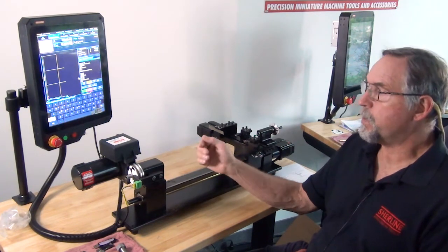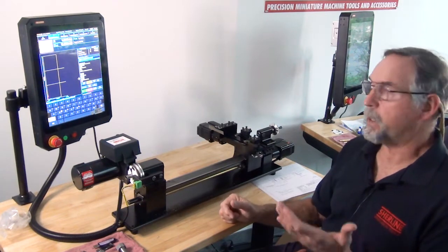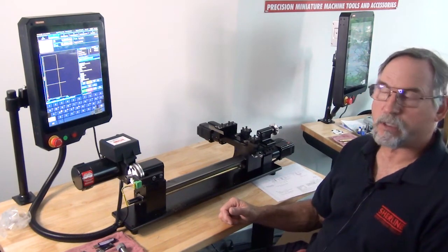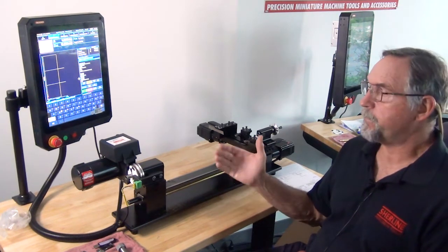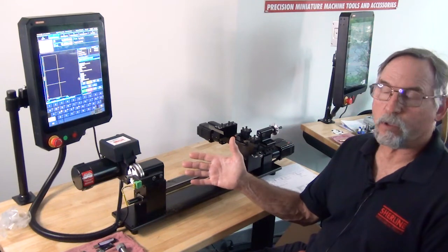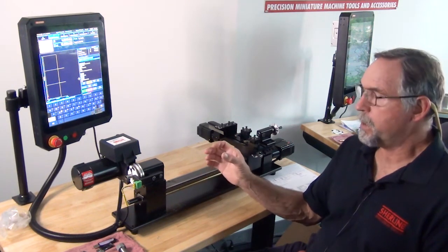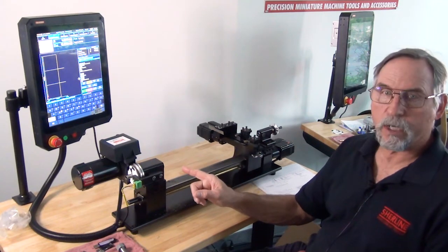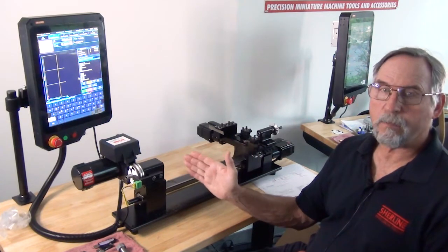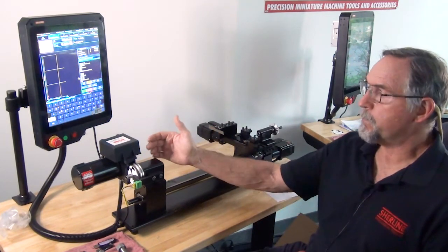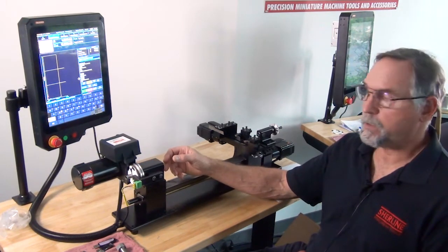Okay, the other one is if you don't use it and you're doing turning operations. Let's say I put in, for a 2-inch diameter stock, an RPM of 1000, and I have a feed per revolution. 1000 at a feed of 3 thousandths per revolution might be fine for my diameter of 2 inch, but as I go into smaller diameters, the feed is still going the same, the RPMs are the same, and the load on the motor is much higher because the RPMs aren't picking up, okay?